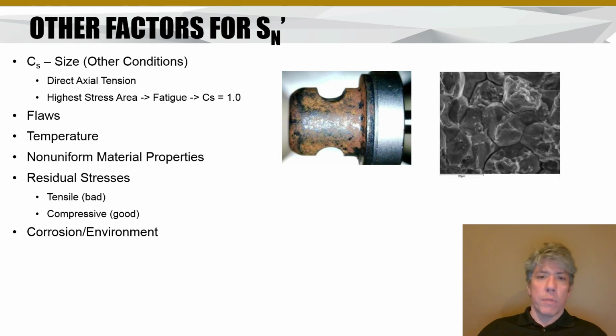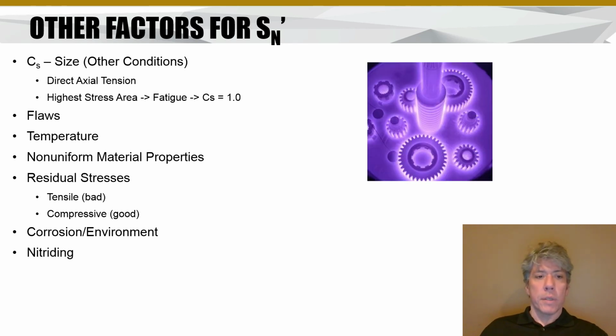But there's also hydrogen embrittlement. If you have a steel, especially high-strength steels, in a hydrogen environment for whatever reason, that hydrogen will basically attack the steel. It'll diffuse through it and cause essentially crystallization of the material, where it breaks apart and becomes brittle and not a very good material for taking tensile loads. So depending on the environment, there can be other things as well, of course, but that can cause trouble that would derate the endurance strength of the material.